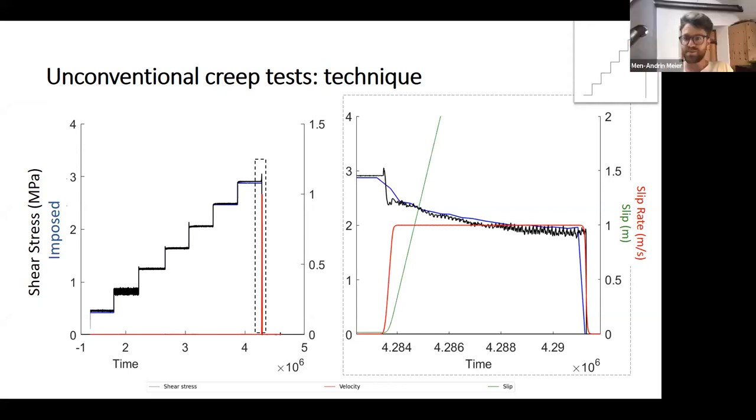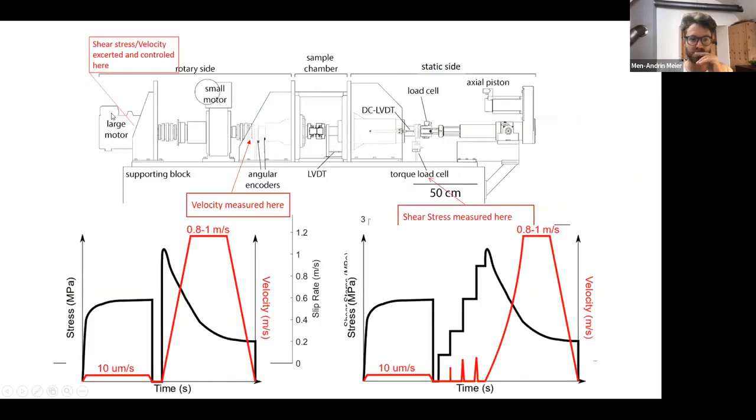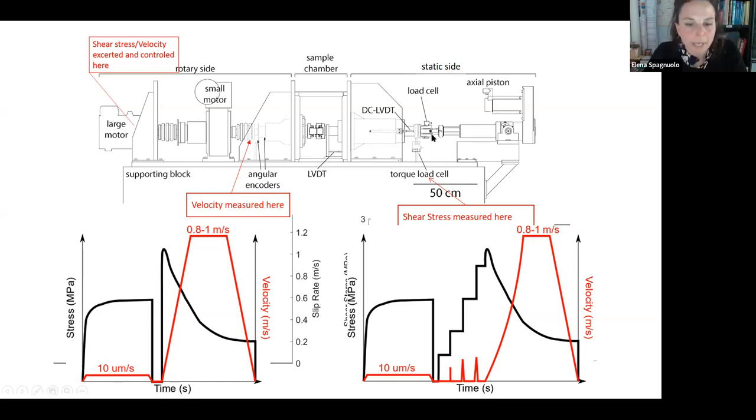A potentially stupid one. I don't understand, how do you directly control shear stress, or do you control it through normal stress? Okay, so the normal stress, it's easier. It's applied here by a piston. This is an electromechanical piston and is controlled here at 5 MPa on 15 MPa, and it's constant during the test. It's kept constant in feedback.